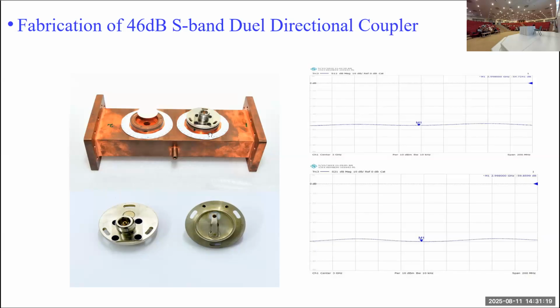Now one port measures the forward power and the other port measures the reflected power. So the trick here is how we can adjust the positions of these two slots, so that one only measures forward power and one only measures reflected power. Then we have to again know the waveguide length of that particular RF which we are passing through the waveguide.